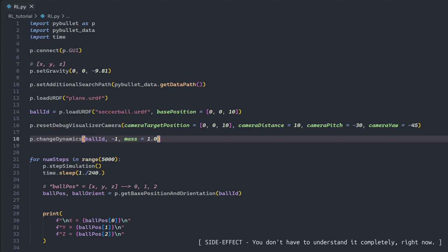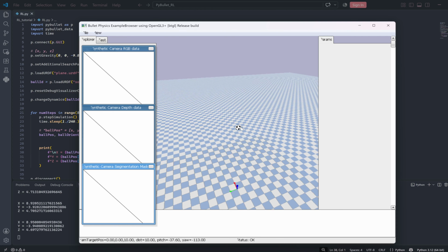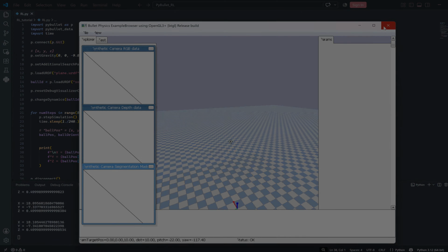And here are the key side effects to know. When you change the mass using p.changeDynamics, PyBullet automatically updates two other properties under the hood. Firstly, the inertia matrix. PyBullet recalculates the local inertia tensor for a sphere of that mass. Secondly, the activation. If the object was sleeping, deactivated to save CPU, changing its mass instantly wakes it up, so gravity acts on it immediately. If you run your simulation again, you might notice nothing has really changed, but the mass has been applied to your object anyway.